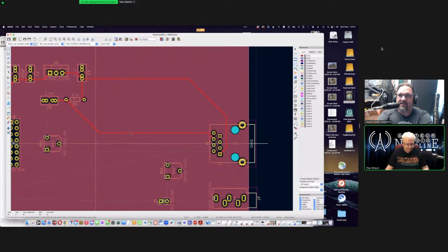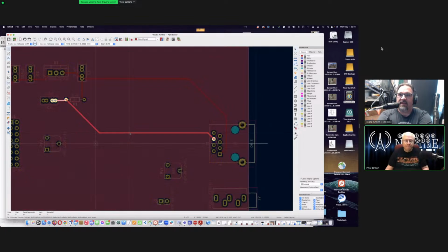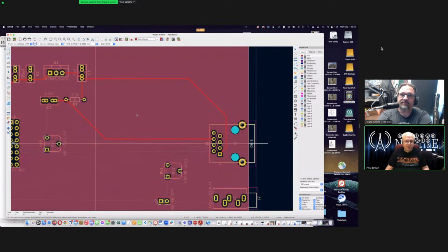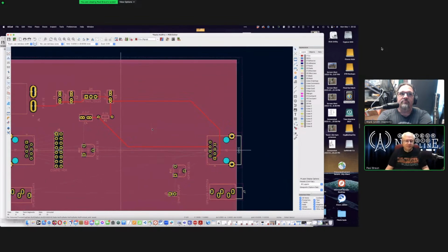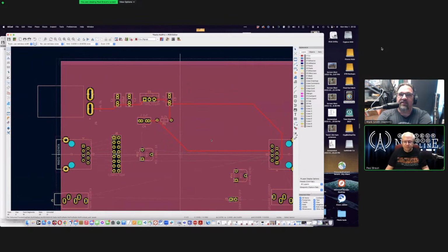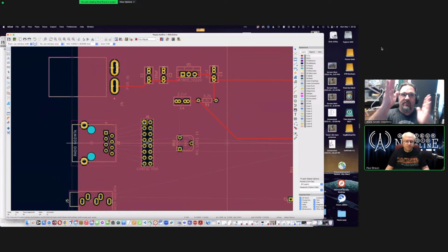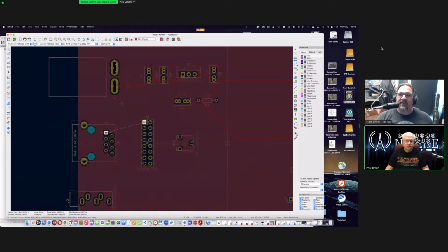Okay. Then hit D and drag it down. Oh, look. Yeah. It's un-straightened. D will move a trace in 45s and 90s. Okay. So since you grabbed that trace and pulled it down, all the connecting traces will move and wiggle along and maintain 45s and 90s and whatnot.